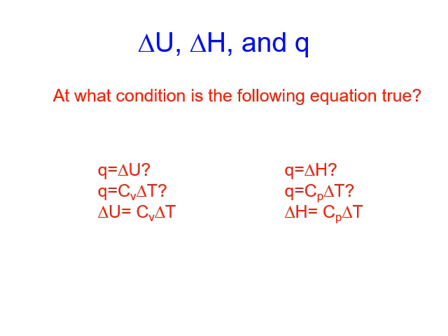When can you calculate delta H by Cp delta T? Well, Cp delta T is the heat. So delta H equals heat, that's constant pressure. And also, this comes from the first law. So delta H equals Cp delta T if it's constant pressure for any gas, ideal or non-ideal. But if it's not constant pressure, is this equation still valid? Yes, if it's an ideal gas. If it's an ideal gas, then delta H equals Cp delta T is always true. It doesn't have to be constant pressure.